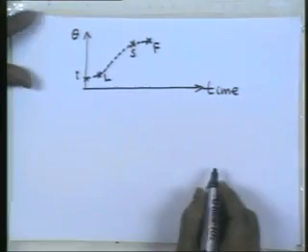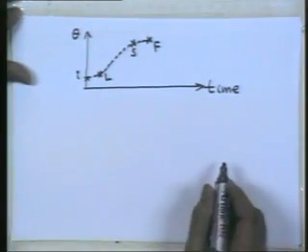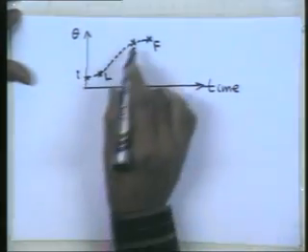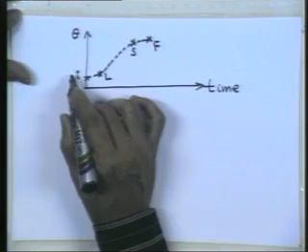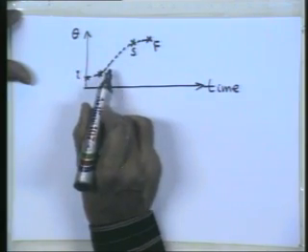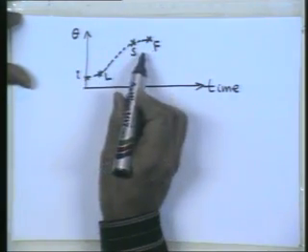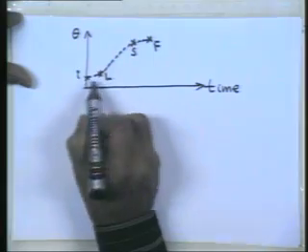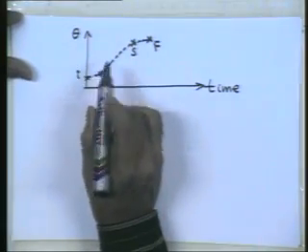So we need to generate 14 equations for fitting a 4-3-4 polynomial through this. Okay. So that we will get a smooth motion from the initial to the final position, with the objective of the pick and place operation of interacting with the environment and the support surface being satisfied.